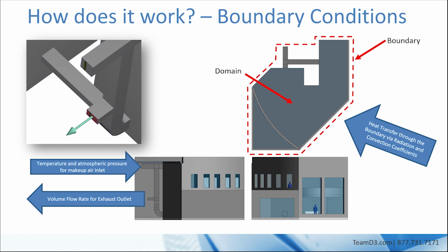Heat is also added or removed from buildings via convection to the outside air and radiation to or from the surrounding environment. These effects are often simplified with boundary conditions, using coefficients to remove, or in some cases add, heat, which are calculated based on assumed environmental conditions, like external air temperature and velocity. This would be done instead of actually modeling that surrounding air. When the effects are not simple enough to replace with boundary conditions, the physics will actually be modeled.